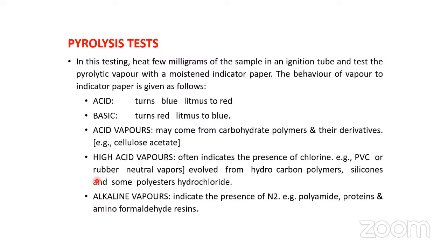Sir, in this, any particle we have to cut and put in a test tube and heat it? Yes, a special kind of tube is available for the pyrolysis test. It is not a test tube. In that, you can insert only a few milligrams of your polymeric sample. After inserting, if you heat the tube or ignite it, some pyrolytic vapors will get created.